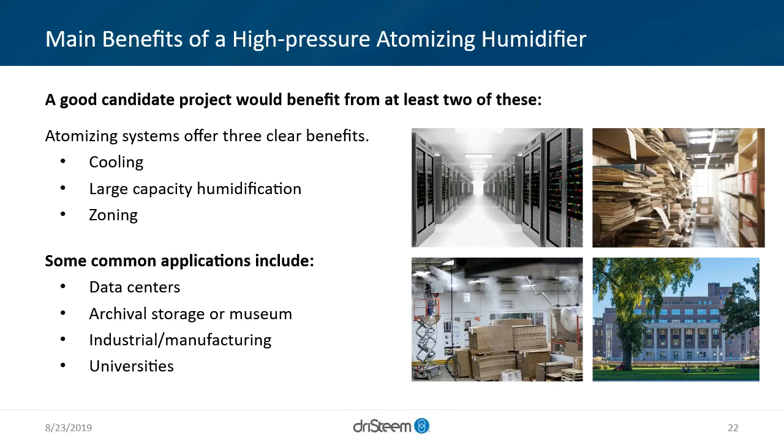And then zoning. Along similar lines of large capacity, if we can have one pump station feed multiple different zones or multiple air handlers, that can really be advantageous in the sense of project cost. So again, some typical applications include data centers, museums and storage, industrial and manufacturing, and universities.